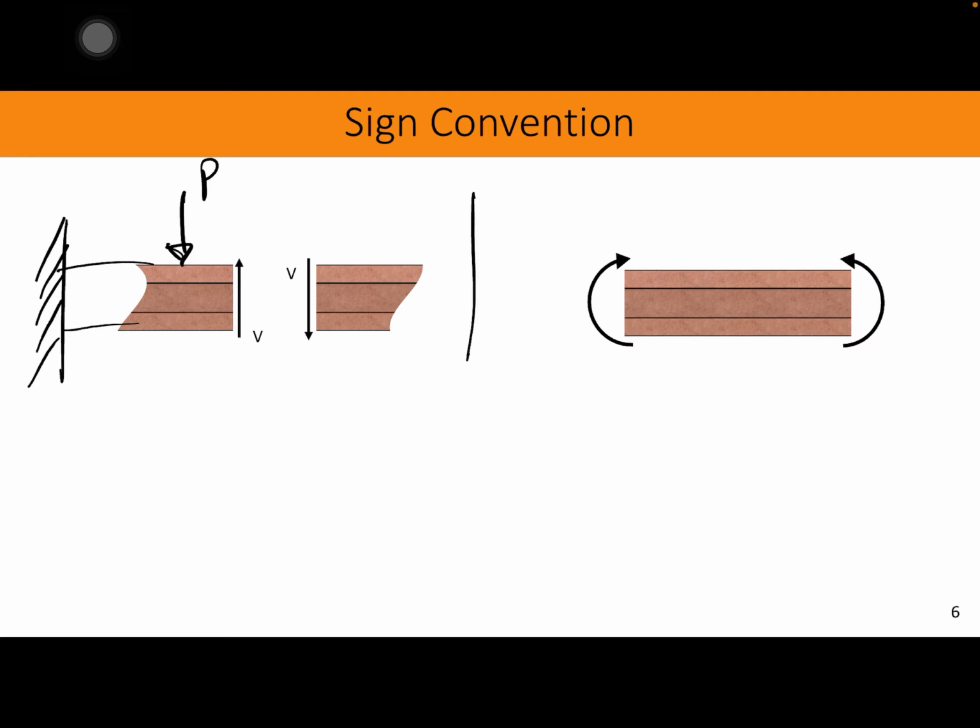And then if you come from the right side, and you have applied the load, you consider the shear force downward is negative. So again, this is nothing but just, when we solve the problem using an equilibrium equation, we just have to think about which one is positive and which one is negative. Even if you get a negative answer, we have to flip the sign, or we have to state that either downward is positive or upward is negative. So we just need to make sure that we are maintaining that sign convention.